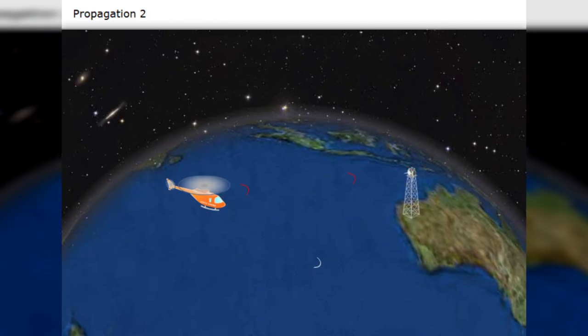Day-night frequency choice. A frequency chosen for daytime transmission may not necessarily be a suitable frequency for nighttime use. This is because during the day, the ionosphere has many layers that absorb the lower frequencies and reflect the higher frequencies. Low frequencies being 2 to 10 MHz, higher frequencies being above 10 MHz. At night, the ionosphere becomes thinner layered, which then reflects the lower frequencies, whilst the higher frequencies pass straight through.